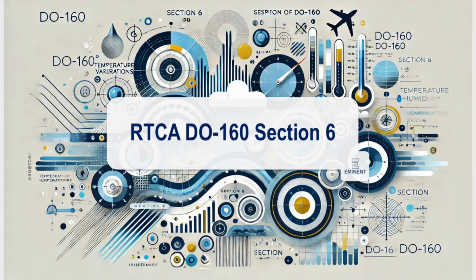Rationale behind humidity testing. Humidity testing under DO-160 Section 6 verifies that equipment can withstand moist conditions that might otherwise lead to corrosion, short circuits, and component misalignment. Testing categories simulate real-life environmental exposure, confirming that equipment maintains its functionality and integrity even in high humidity or condensation-prone areas. FAA guidelines and customer specifications determine the appropriate category, ensuring equipment is suited to its operational environment and enhancing safety.